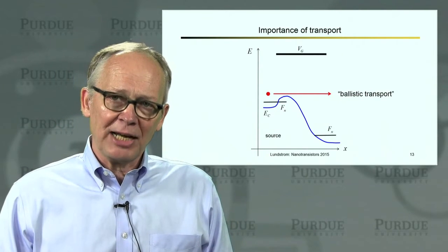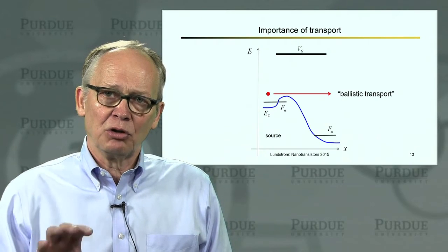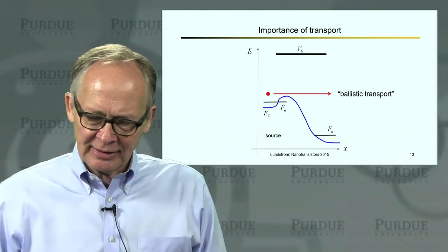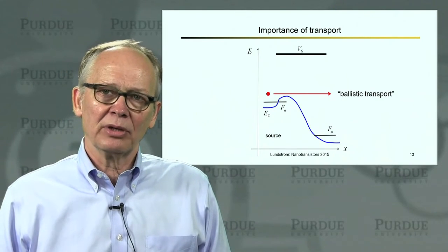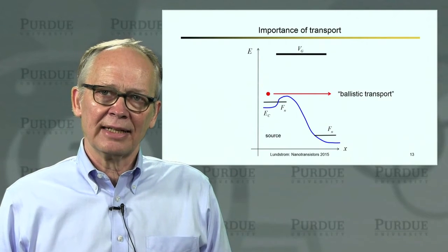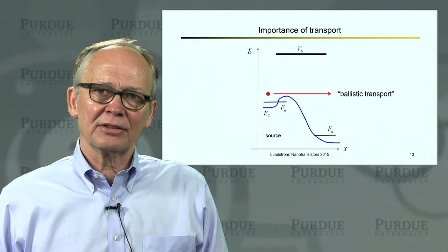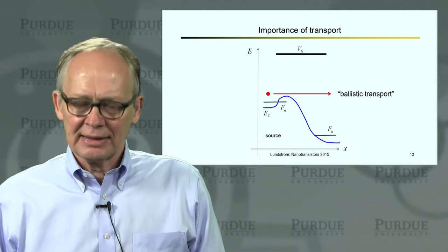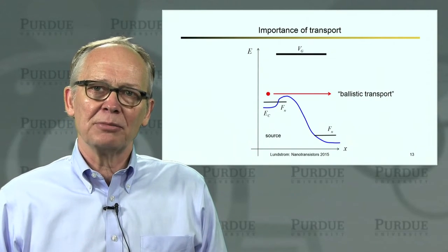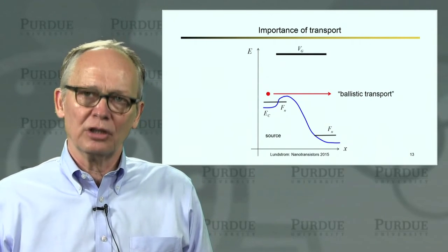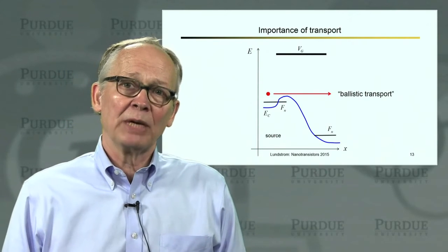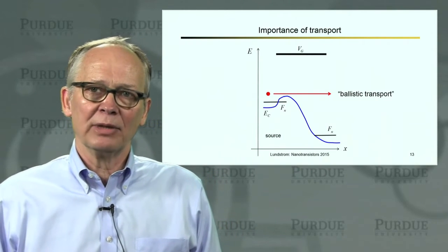The particular shape of the IV characteristic is controlled by how we manipulate these energy barriers. And that's an extremely important thing for transistor design, to be able to design the electrostatics of the transistor such that we can manipulate these energy barriers appropriately and get good IV characteristics. That's why we've devoted an entire unit to MOS electrostatics.